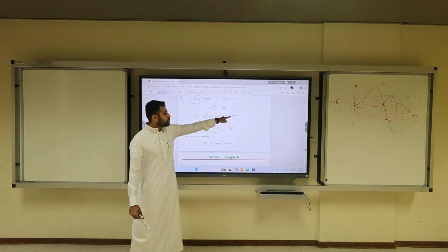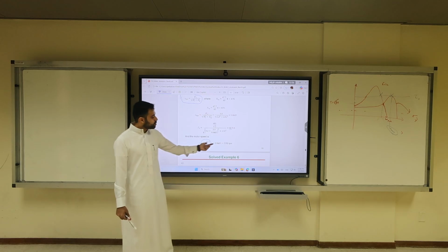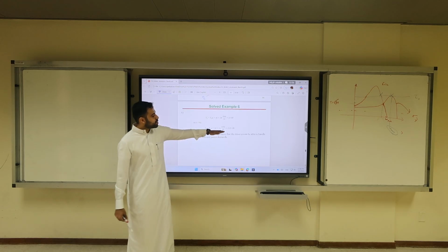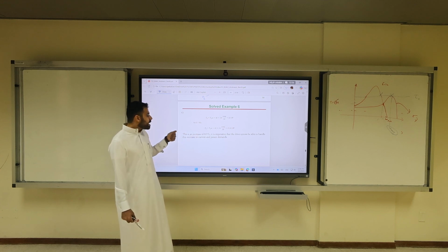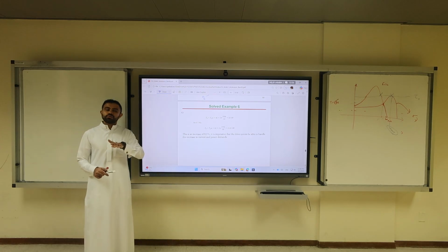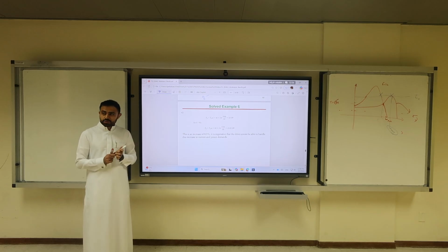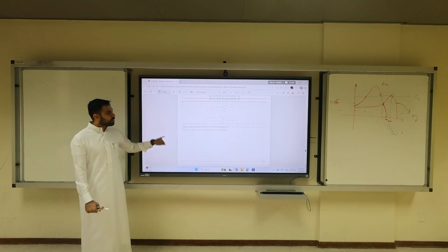This is how we calculate it. You get the slip, you convert the slip, you calculate NS2, the second speed. You get the speed 3792 and you get the power 23. So that's an increase of 8.3%, which means the drive system is barely able to handle this load. Okay? So this is your limit. If you drive any frequency above 67, your load will not be driven. But is this a good speed to operate at? No, because it has very high current, it's not stable. With mechanical losses, you may not be able to drive the load.